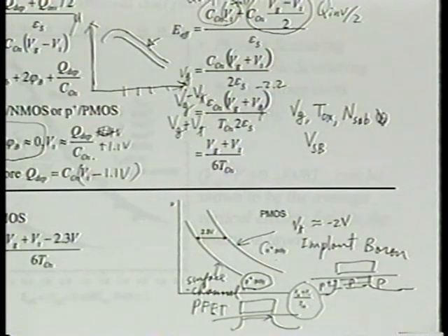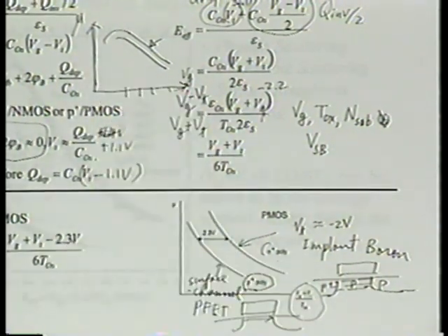Okay? This last picture is a very interesting picture. I actually like that picture, but I can tell you I've never seen anyone try to analyze it theoretically. In other words, if we knew the location of the conduction charge as a function of Vg, from the quantum mechanics analysis, we know the charge thickness, we know the centroid, right? From that, can you figure out why the surface roughness should give us a mobility versus Vg in this manner? If you can derive that, it would be very good to use it to confirm that the explanation of the measured data is due to that mechanism, to see if it agrees.